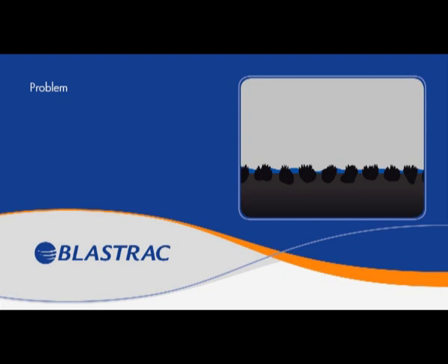Over a period of time, and depending on the type of covering, aggregate, and the frequency of traffic, the rubber marks left by car or aircraft tires will gradually make the aggregate smooth and eliminate the micro texture. Soil on the road or runway surface will eliminate the macro roughness.